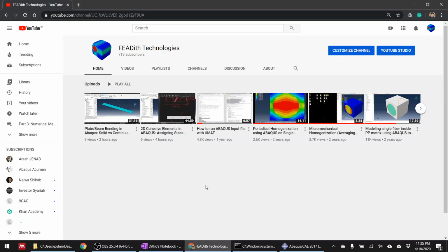In this tutorial, I'm going to show you how to use the ductile damage model in Abaqus. It has usually been used for modeling damage in metals or damage in polymers, but it was actually originally developed for metals. But of course, it can be used for polymers as long as you fit correct parameters.